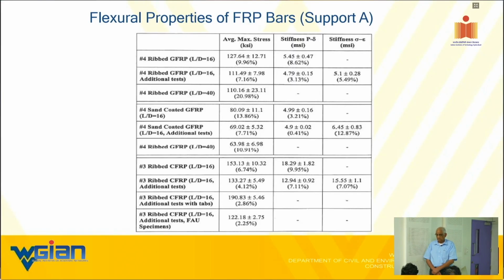I multiply that with 5,000 psi, and I'm suddenly talking about a 200 kip machine. I have a 750 kip machine, but 6 by 6 is nothing. When you scale it up to 12 by 12, that is 144 multiplied by 5, that's 750 kip loading. That is where it's falling apart. We can do it, but it's very expensive.